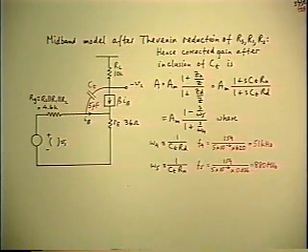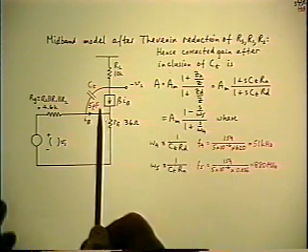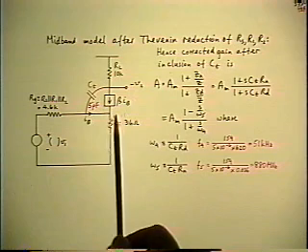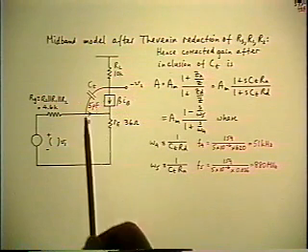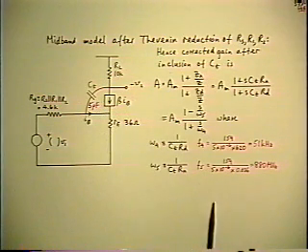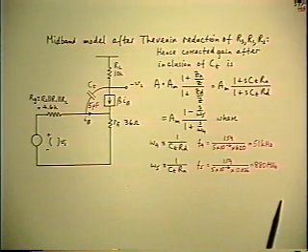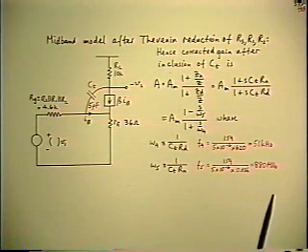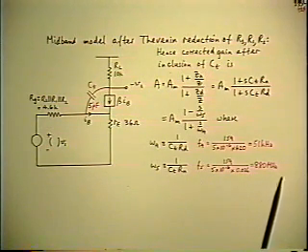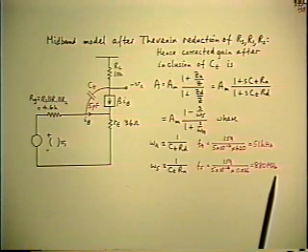So one thing to think about now is right half plane zero in this stage may not be of any concern, but if you have widely different numbers, it may come into having some effect, and it may be the cause of some difficulties you might have had and not really known why.